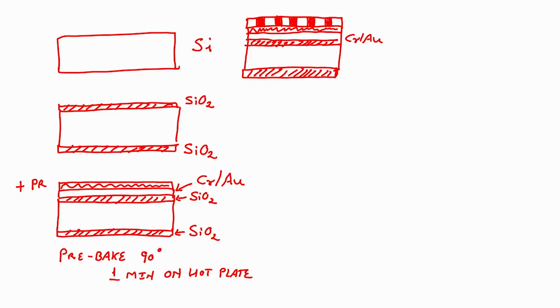And then I exposed this using UV light. After doing that, I unloaded the mask and developed the photoresist.